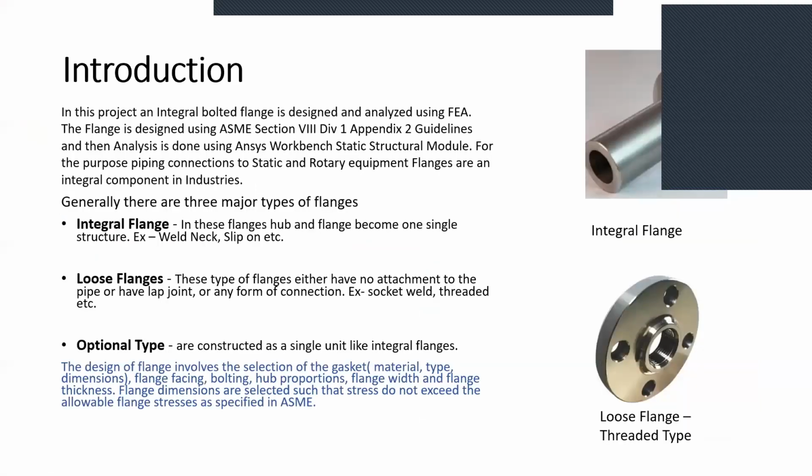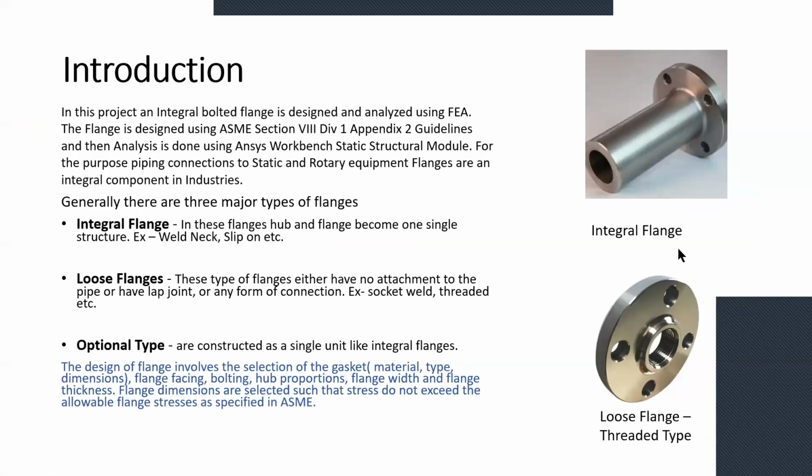Moving on, firstly, I would like to have a brief introduction about the flanges. The flange is designed here on the basis of ASME Section 8 Division 1 Appendix 2 guidelines, and the analysis is done using Ansys Workbench static structural module.